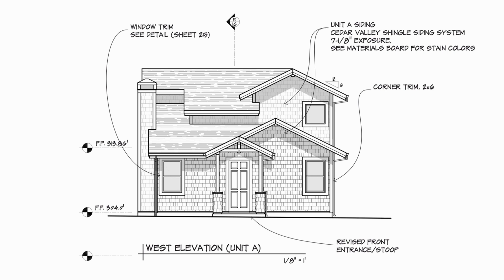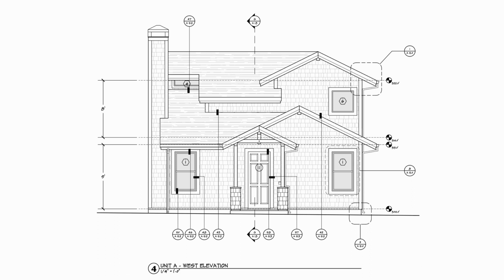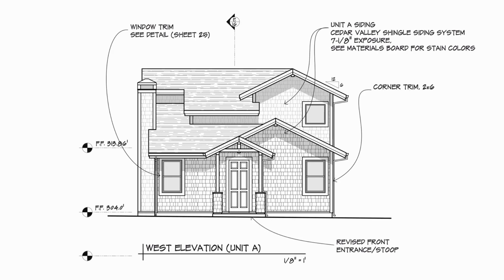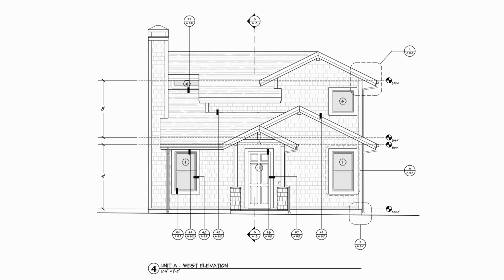When we get to the construction drawing, which is the next one, so all these are the same building, same elevation, this is a technical drawing. This is about how do we build this particular building. Notice that the line weights are still kind of there, but they're really underemphasized now. It's not about that anymore, it's about all the details. It's about all the little dashed lines, the hidden lines, the section lines, the detail marks. That's what it's about. That's what I'm trying to read in this drawing. So there's a purpose for each one of these elevations, and my drawings are responding to that purpose. So I'm spending more time with the line weights on this than I am with the line weights on that.